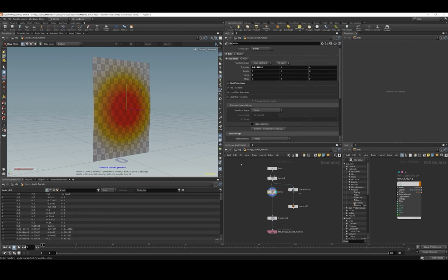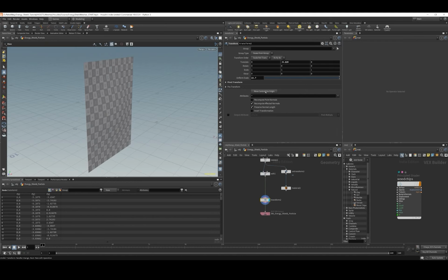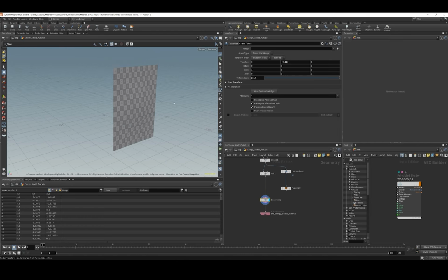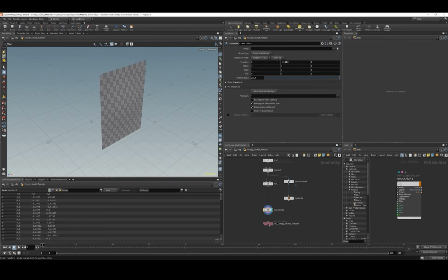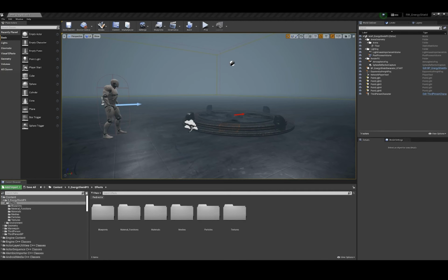And then the last thing I did was I just transformed it. I just moved the centroid to origin, made sure it was in the center because these are going to be rotating later on. And then I just gave it a scale of 22.7. I want these to be kind of small, and then just save those as well and give them a name. And those are our meshes.